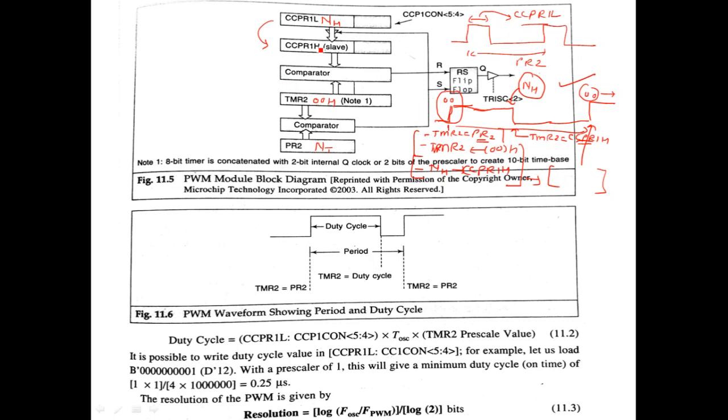Yes, so here what happens is that the count you want to adjust for deciding TH, that count, as a programmer, you should keep in the CCPR1L register. As the cycle begins, for example here, this content is copied here in the CCPR1H register, and actually that register is compared by this comparator with TMR2.